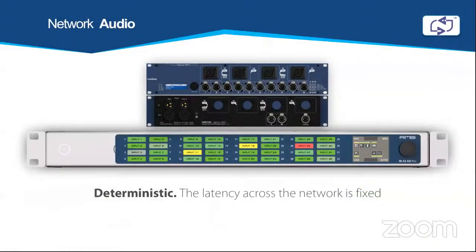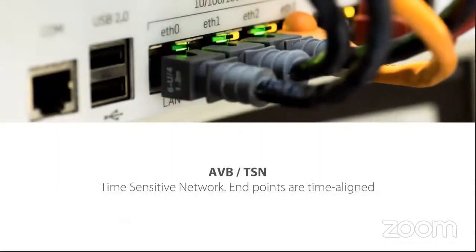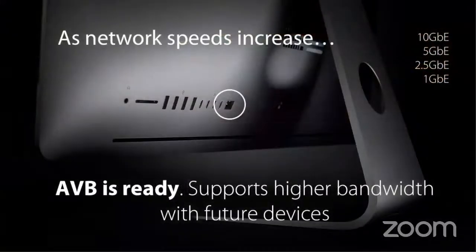Now, the AVB protocol is deterministic, so the latency across the network is in fact fixed. As I said earlier, it's a time sensitive network, so all of the endpoints, the listeners and the talkers, are all time aligned. And because it's an open standard, it supports higher bandwidth with future devices. So as the network speeds increase in the networking world, AVB is ready and should be able to be very easily adopted in those scenarios.